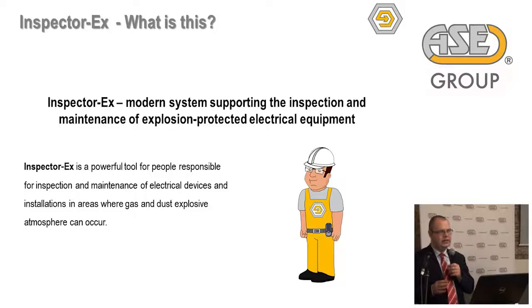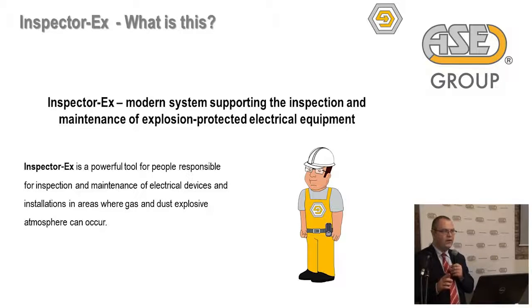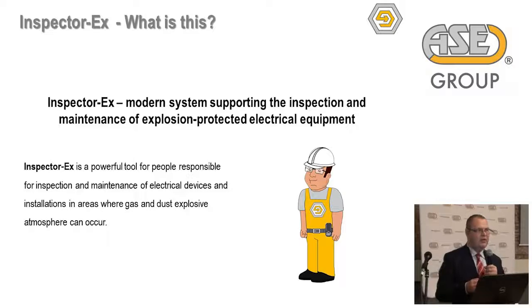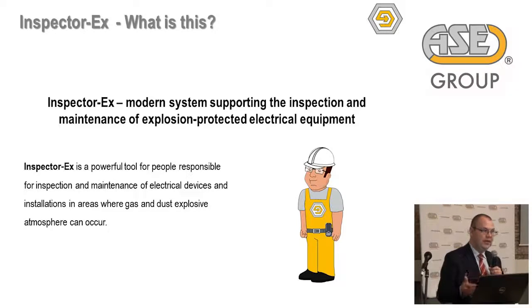This is just part of the life cycle of a complete installation, because over time we have to do maintenance, and maintenance for explosion proof equipment is very important, because good maintenance determines whether we still have explosion protected equipment or not, if we do not make any inspection over time.